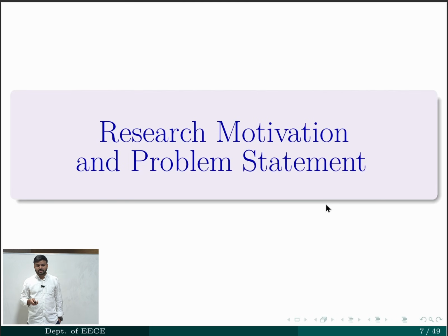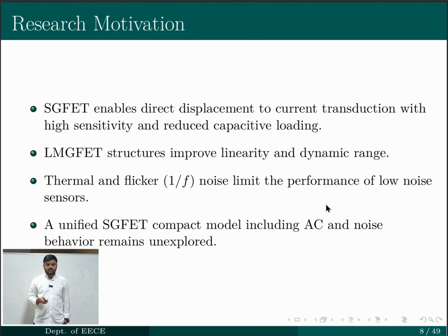Now research motivation and problem statement. The research motivation is that SGFET enables direct displacement to current transduction with higher sensitivity and reduced capacitive loading, and the LMGFET configuration, meaning laterally movable gate field effect transistor, also improves the linearity and dynamic range.